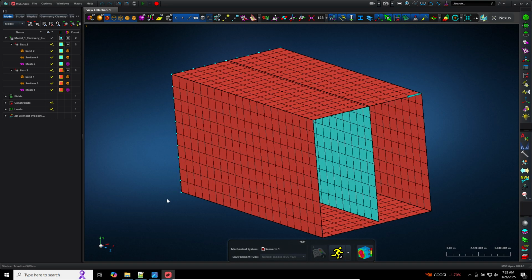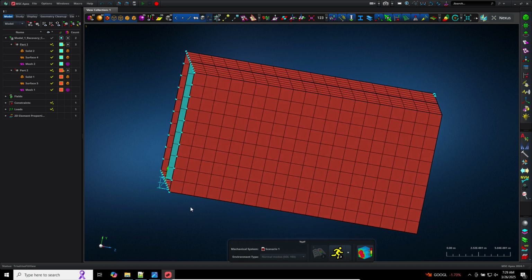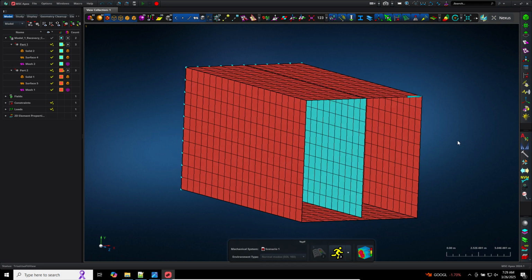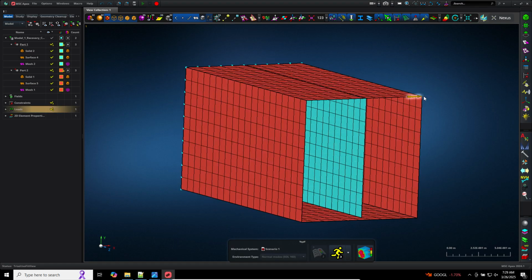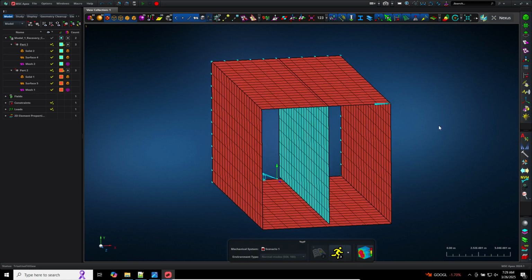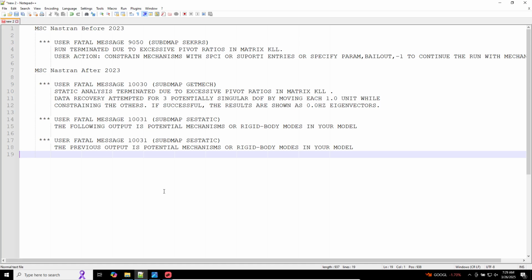This is the finite element model we are working with today. Basically, you can think of this as a cantilever beam. One side of this beam is fixed, and on the other side, the free edge, we apply a force at this corner, like you see here. When we look at this mesh, it looks like everything is connected together. This message commonly happens when a piece of the mesh is not attached.